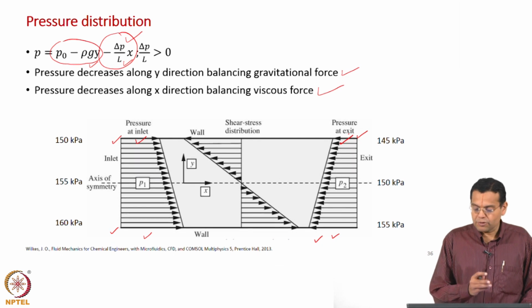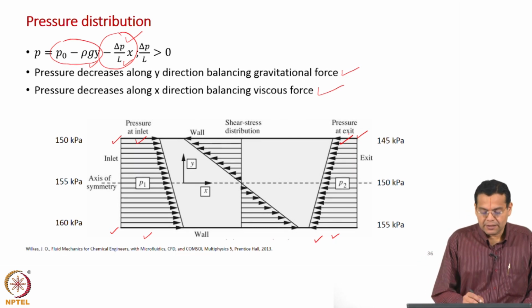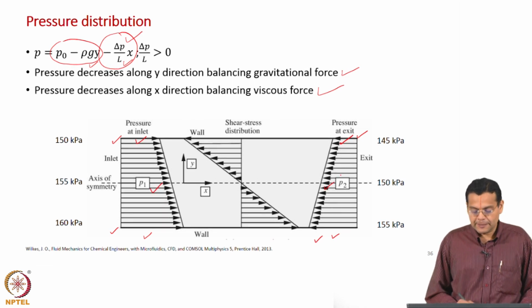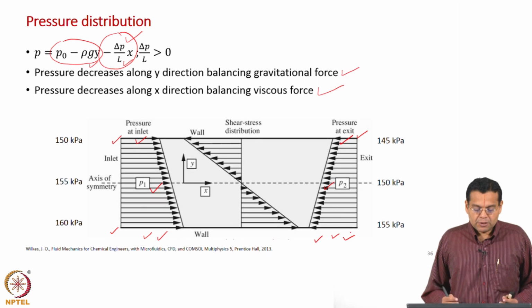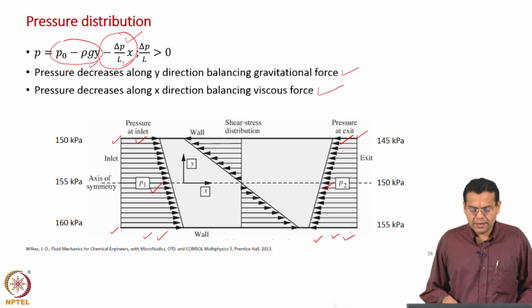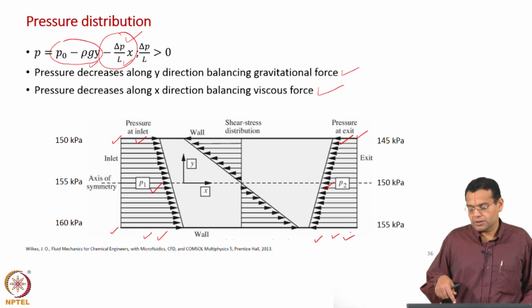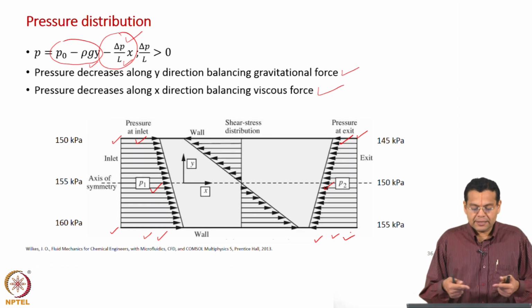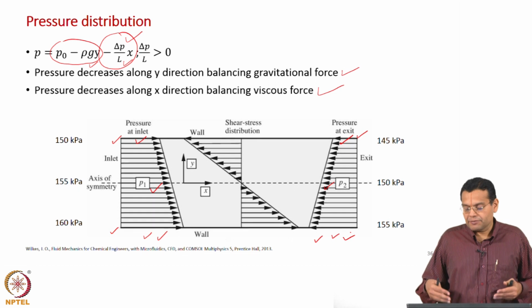And that is of course constant throughout the height, whichever position you take, there is a decrease in length, and the decrease is also constant, continues till the bottom, okay. So, let us quickly repeat, the arrows are towards each other into the control volume because it is compressive, and pressure increases as you go down both at the inlet and the exit, and in terms of magnitude, the inlet pressure is more, the outlet pressure is less, and that is shown in the length of arrows as well, and that difference is same at any vertical position, okay.